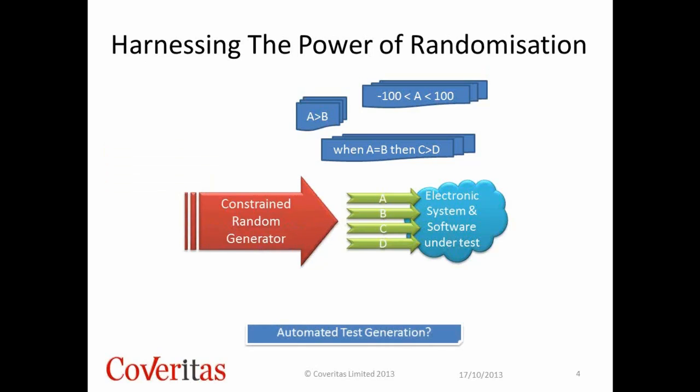So in the hardware world, this was done with a concept called constrained random generation, and that's something that I was involved in from 2000 onwards. The idea here was that we generate random stimulus, but it obeys a set of rules. And each time we call a function or generate data structures, we can generate that data structure obeying that set of rules. Now, naively, I guess, when I started applying this to software, I thought, yeah, that'll do. I can apply it to a software tool chain, and I should be fine. We should be good to go with software engineers. I think I learned probably more slowly than I ought to have done that that wasn't enough.